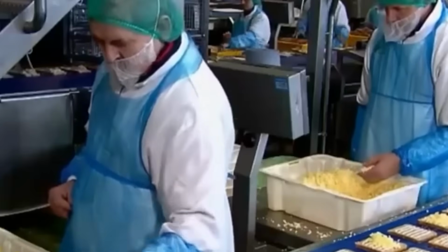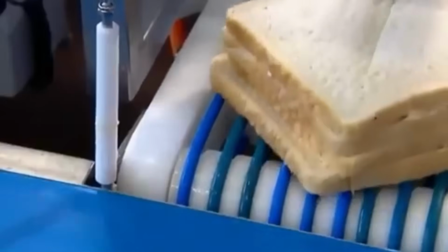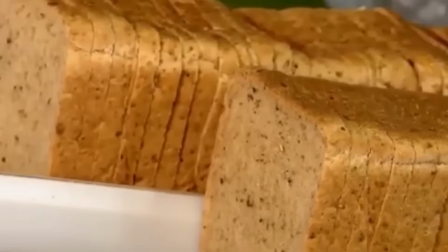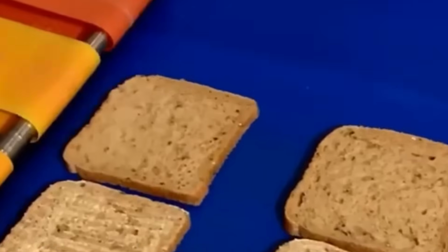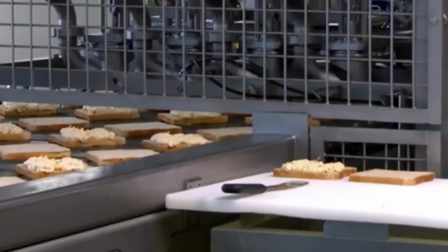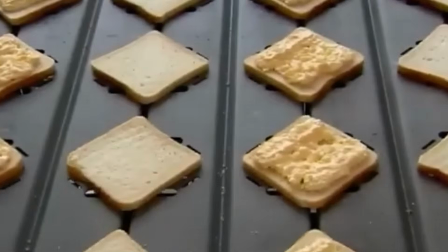The cheese is picked and placed onto the meat with exact positioning, sometimes staggered depending on the sandwich style, and lightly pressed to ensure it conforms to the underlying surface without folding or hanging over the edge. The equipment adjusts for slice fragility using low-pressure vacuum heads and static control to prevent light cheeses from sticking to conveyors or deforming during placement.